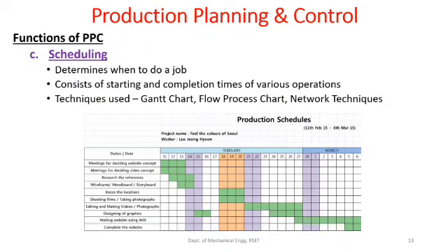As I told you, in manufacturing a particular product you might have to use various manufacturing operations, and these may be done at different times. So there is a time at which a manufacturing operation starts and a time at which a particular process ends. This is recorded in scheduling. Scheduling basically allots a time for work to be carried out. The most common techniques used for scheduling are Gantt charts, flow process charts, and general network techniques.